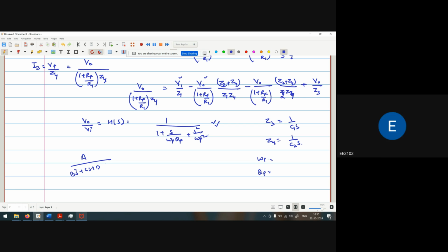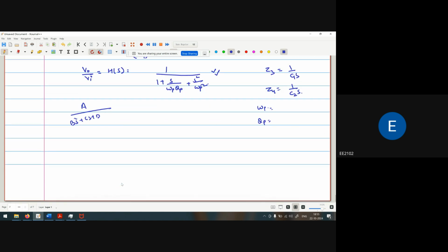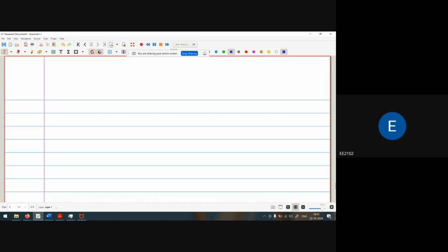Actually, basically, what we consider is that when the transition is done, for any case, not only for the filter, like for example, I'm going either from the maximum to minimum, or from minimum to maximum, always consider that the duration will lie from 10 to 90%. 90% and 10%. Always consider this value. Now,